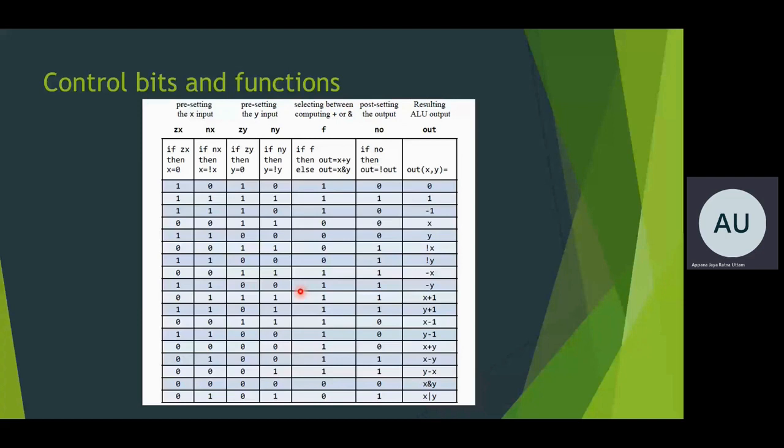So if we need the 0 implementation, we can choose Mux, and if we need a negation implementation, we can use Not and Mux. And if you need to choose between Add16 and And16, you can use Mux16, Add16 and Mux16 again. If you need negation, we can use the Not16 gate which we built in the first project. And to indicate if the number is negative or 0 by the method of two's complement, we can use Mux, Or and Not, and we can give out the ZR and NG values.